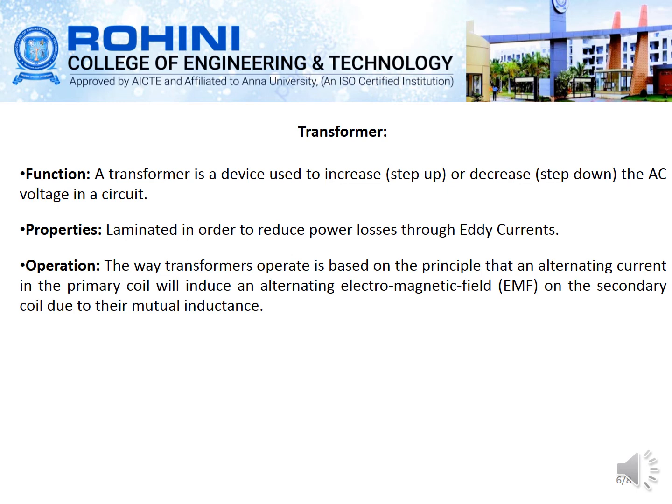When it flows to the rectification, it is converted into a DC supply, but it still contains some ripples, that is, some distortions. So the smoothing filter acts as a noise removal or pre-processing stage, removing the ripple factors present after the rectifier.